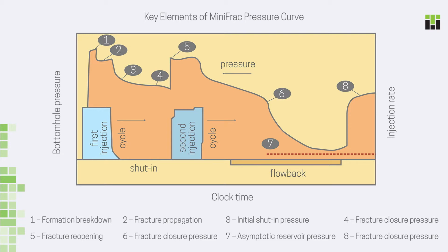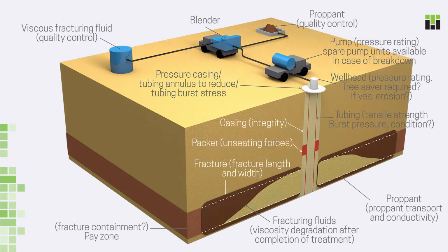Instead of several hundred or even thousand cubic meters of technical fluid, which in this case is called fracturing fluid, we try and pump in less than 5 cubic meters. This is called microfrac. Or less than 50 cubic meters. This is called mini-frac. From these tests, we obtain valuable information such as rock fracturing pressure, fracture propagation, and fracture closure pressure, as well as minimum stress in the wellbore area. After a mini-frac or microfrac, we are ready for the main operation.